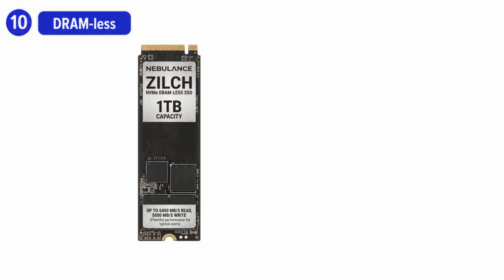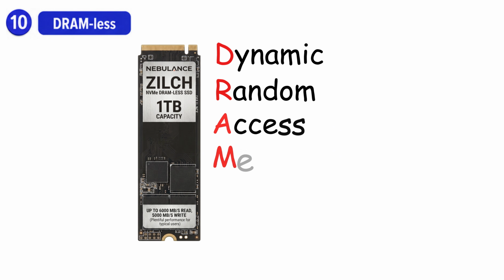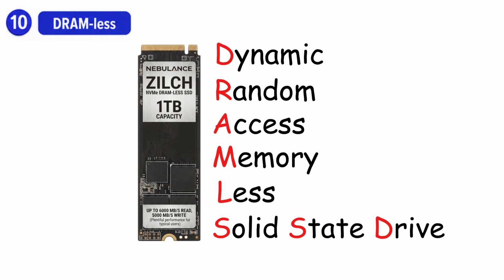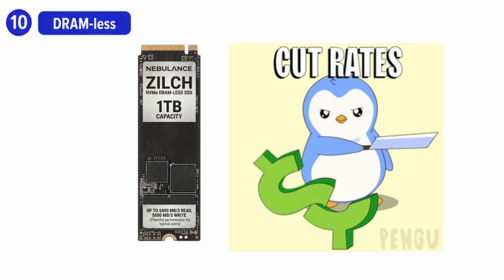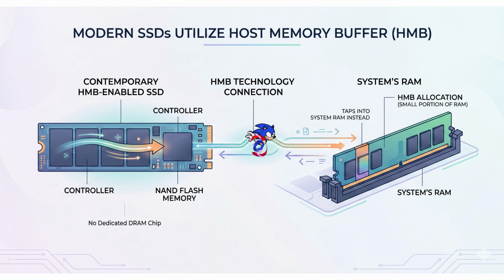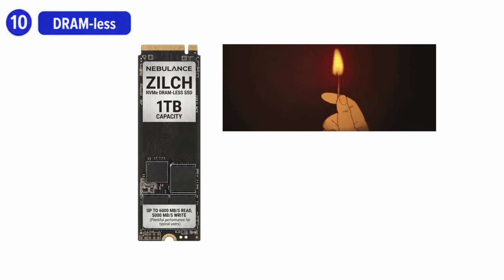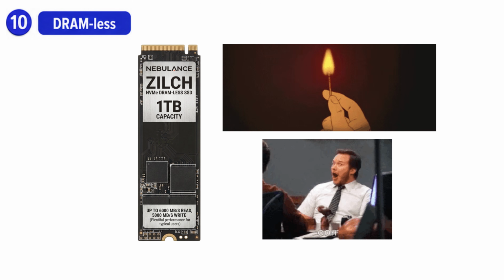DRAM-less SSD. A DRAM-less solid-state drive forgoes dedicated DRAM cache to cut costs. Many contemporary models utilize host memory buffer technology, which taps into a small portion of the system's RAM instead. For lighter workloads, performance can be surprisingly similar to that of DRAM-equipped drives.